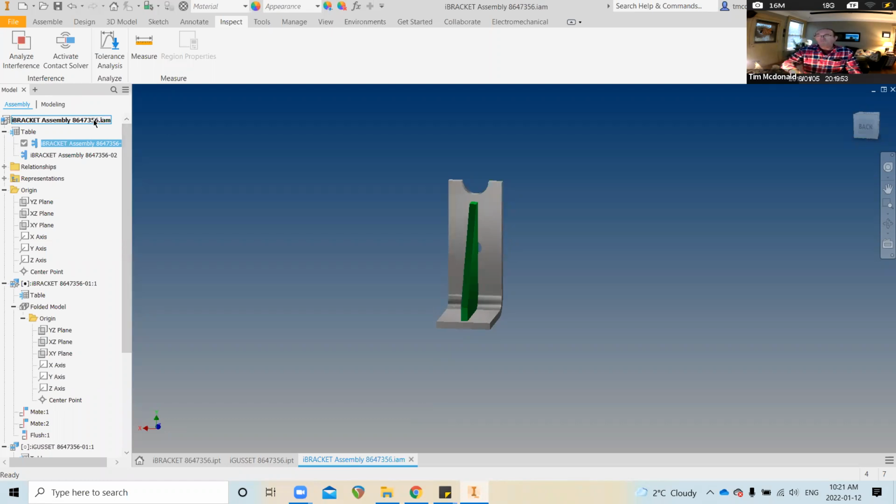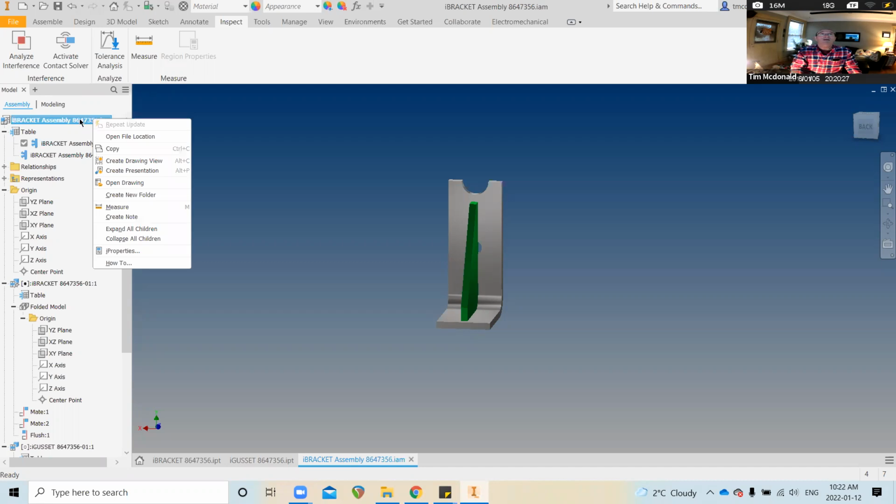IDW is my preferred format, and I will normally ask you for IDWs because they are smaller and they are more adept to converting within the Autodesk line of products. DWGs are bigger, bulkier, and do not have as much transferable specific intelligent information from Inventor to DWGs. So I'm going to right mouse click on my IAM at the top level here and create a